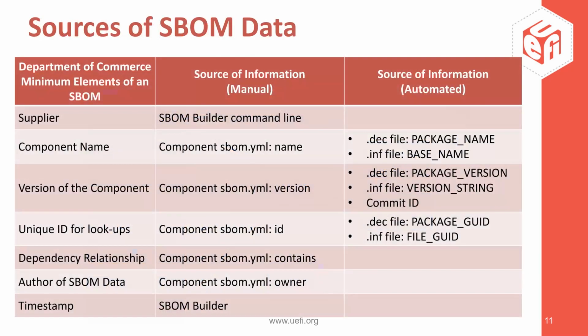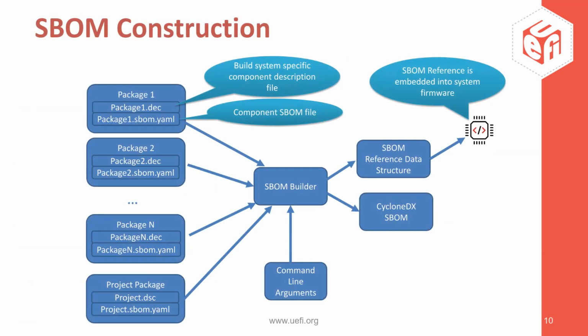So just before going to the next slide, the SBOM reference data structure. This is essentially a piece of information that uniquely identifies the SBOM, and it goes into the ROM image. As Brian also mentioned, it's an implementation choice whether to include the SBOM directly into the ROM image or the reference data structure. At this point, we believe the reference data structure is a more practical approach.